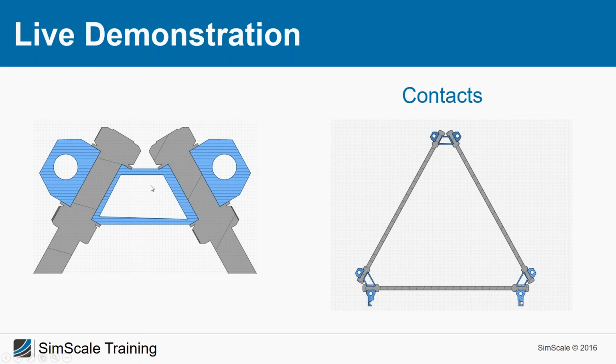And now in the end, contacts are just defining how the assembly should behave in the case one part of the geometry is deforming or moving. And if we take a look here, we have first of all a contact between the inner surfaces of this connector and the outer surface of the rod. We have the same on the other side. And if you think right now, it seems to be defined, so we cannot tilt it, but we could still move it along this axis.